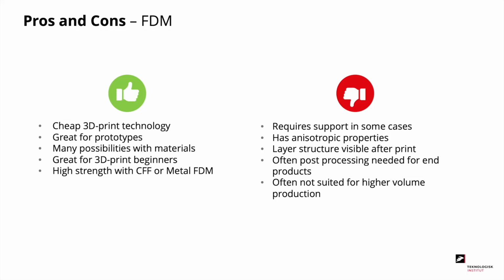Among the downsides, we have the need for support structure, and we have the anisotropic properties. Also, the layer structures are visible after printing, and it requires some post-processing if you want nice surfaces. And finally, it's not suited for high volume production due to the slow printing time.